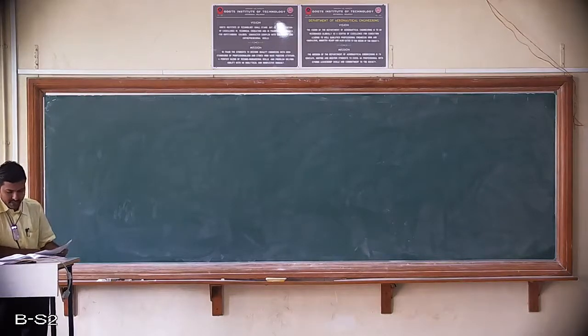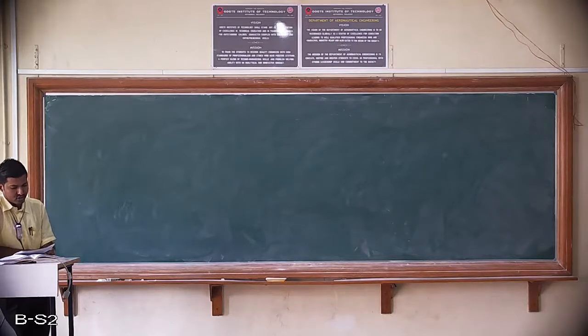In a spring-loaded governor of the Hartnell type, the lengths of the horizontal and vertical arms of bell crank lever are 40 mm and 80 mm respectively. The mass of each ball is 1.2 kg. The extreme radii of rotation of balls are 70 mm and 105 mm. The distance of fulcrum of each bell crank lever is 75 mm from the axis of rotation of governor.